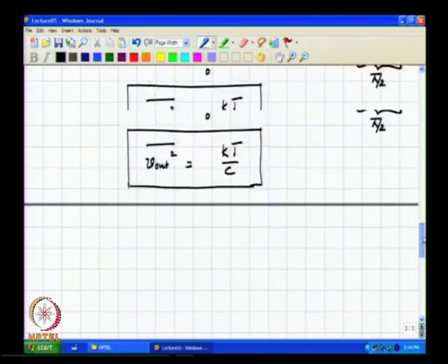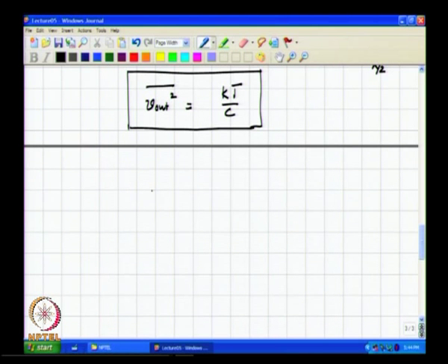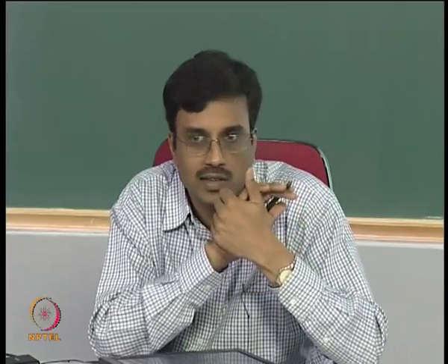So, in English what this result means is that if I took a track and hold with 0 input and a capacitor, the switch can have an arbitrary resistance, and because of the noise associated with the resistor of the switch, when I open the switch, when I transition from the track phase to the hold phase, the voltage stored on the capacitor is not 0, which is what one would expect for a noiseless situation.